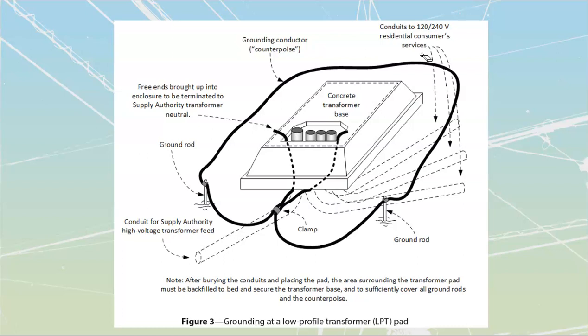There is the depth, these things do have to be a foot underground. They're going to be covered with gravel to provide good drainage. And they do have to be at least 900 millimeters, that's going to be 3 feet, from the pad itself. We do have to keep them circled all the way around. If there is excess length, you're not allowed to cut it off.